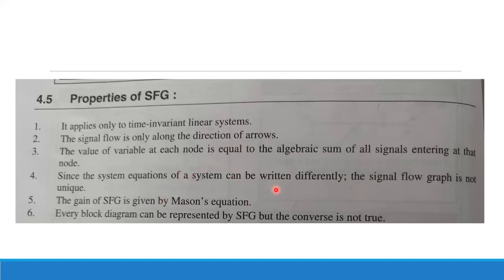In a block diagram, we reduce the blocks by different rules, for getting the total transfer function of the system in a single block, so that we can solve it with the values of input and the transfer functions. Similarly, in a signal flow graph, we do not reduce them. We use Mason's gain formula for calculating the overall transfer function of the system.